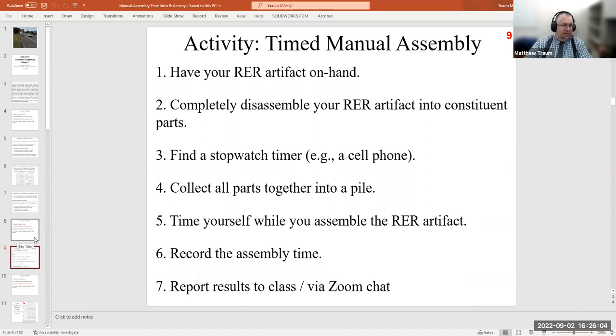Somebody has 7. Oh, you might have 2 gaskets. Yeah, there's 2 gaskets there on the bottom where it threads onto the hose. So I assume just use one. Yeah, just use one. The second one is a replacement, which is sort of interesting because all of the hose nozzles came with 2 gaskets. And so in a way, that's sort of a message from the manufacturer telling us where they think the first failure mode is going to be.